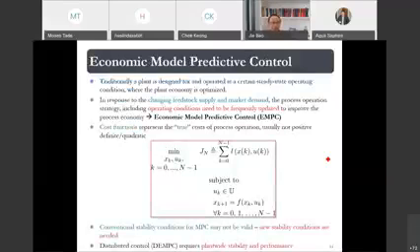Speaking of model predictive control, recently the trend is that a lot of emphasis has been focused on economic model predictive control, because in model predictive control, you can minimize the cost function. And just now in my previous slides, you saw that the cost function is a quadratic function of the error and control action, or a quadratic function of state and control action. So it certainly begs the question, why not put in a cost function that represents the economic cost of running a chemical process? So the cost function ideally would have a unit of dollars.